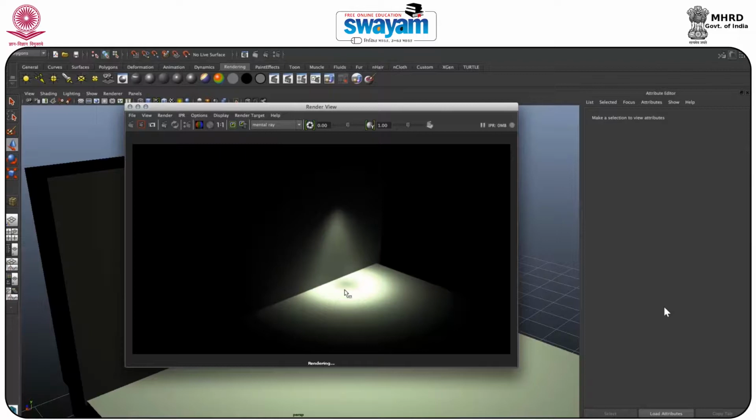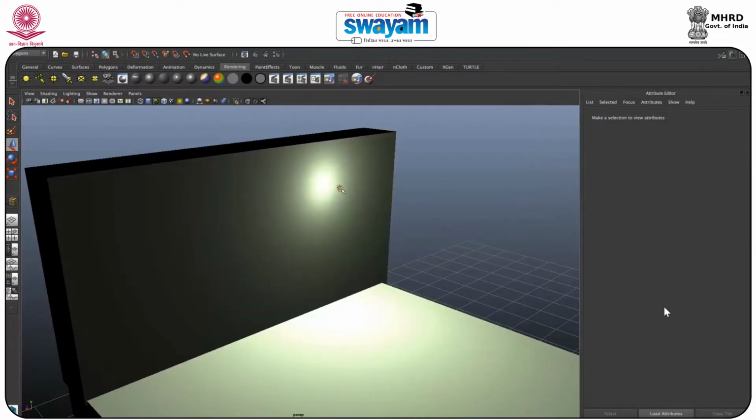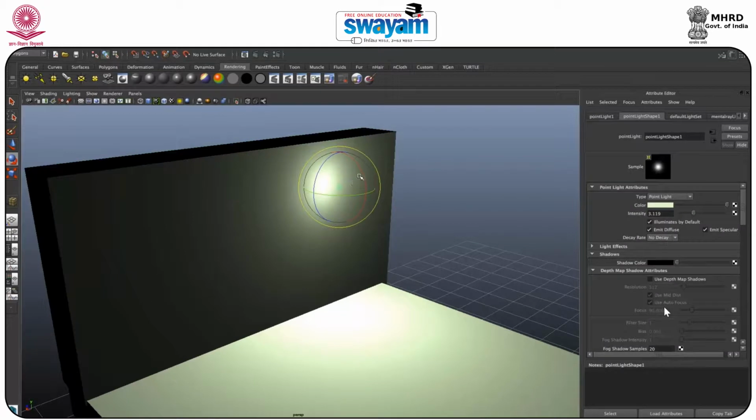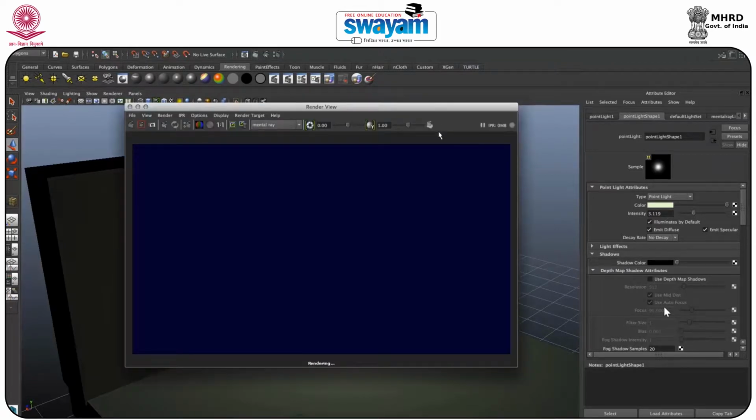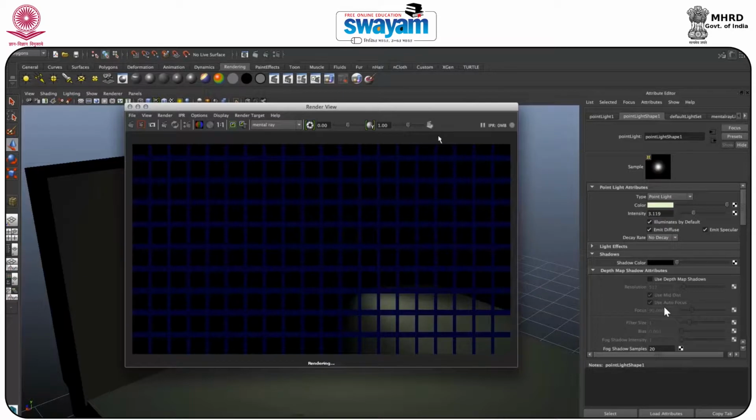Here you have maximum intensity, and if you want to rotate it, you can definitely rotate your light like this. If you go down, see, now it is off from the top because we have rotated the light and it is focusing on the ground. Like this you can work quite well. We will discuss IES light in the exterior also, so let's meet in the next session.